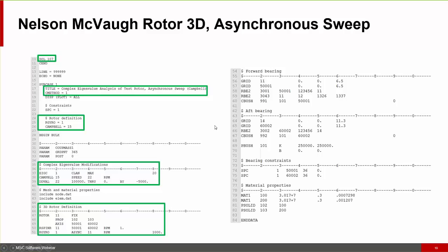What I'd also like to highlight with this slide is that any particular rotor that you build afterward could be wrapped around with this script, if you will. And what I believe is that these scripts have a big advantage in that you can apply quality control against various rotors quite nicely with the clean organization of Nastran decks.